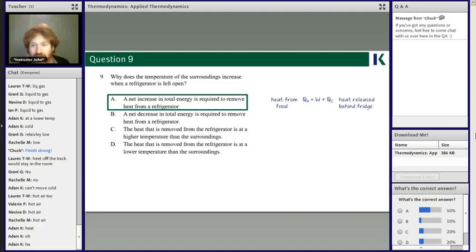We had most people going for A. We were kind of split across the board. But you got it. The whole idea is that in order to create a cold system, it's thermodynamically not spontaneous at all. So you got to actually put energy in to make that happen. So the heat that's blowing out the back of the AC unit is both the heat that it's sucking out of the house, right? Because it's absorbing heat where only heat moves, as well as the heat from the socket in the wall, sucking energy out of that.